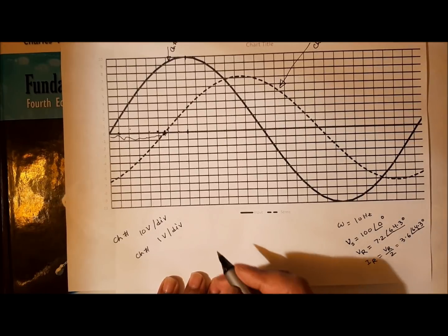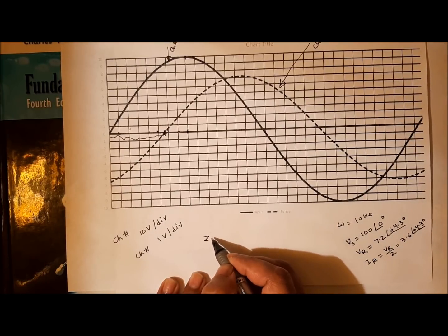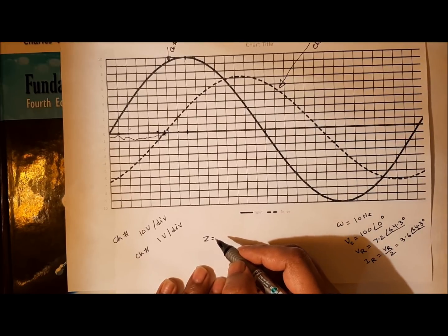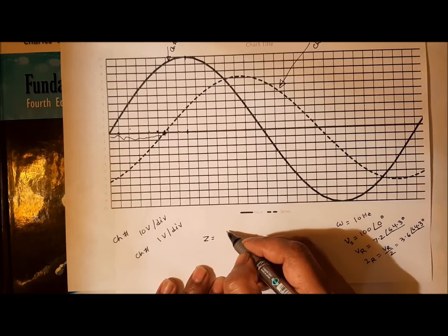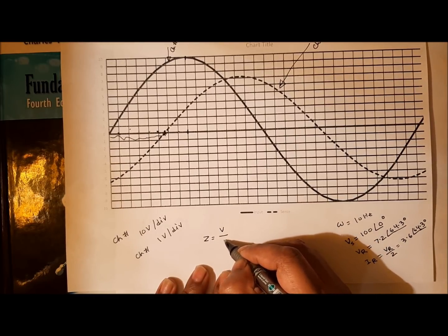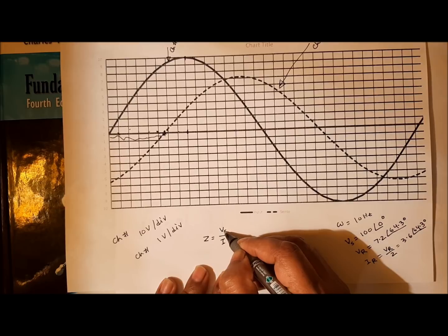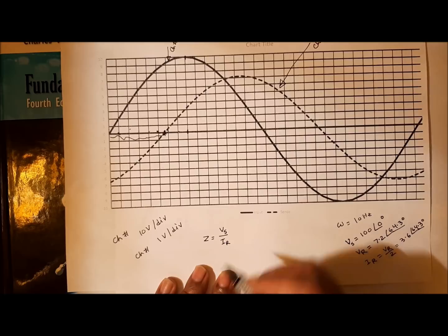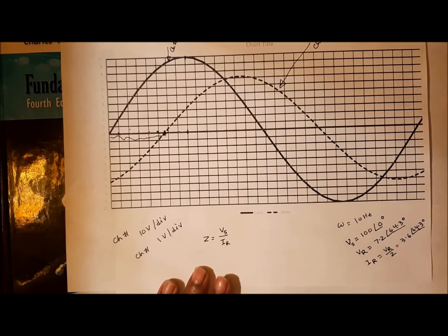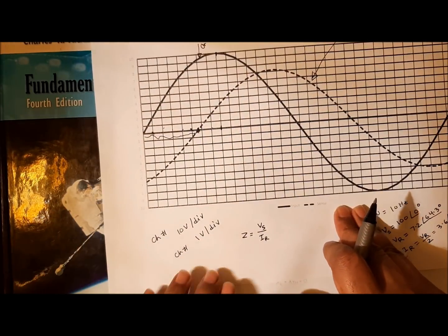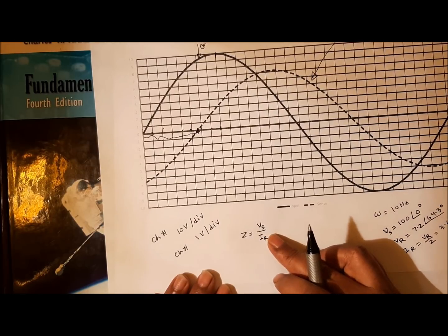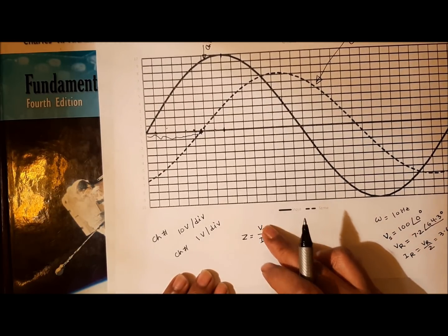Now we can easily compute the impedance. So the impedance Z is the voltage over the current. We got the source voltage over the total current IR. As it is a series circuit, you see the box is in series with the sense resistor. So the current in the resistor will be the current through the box. So we can find Z.